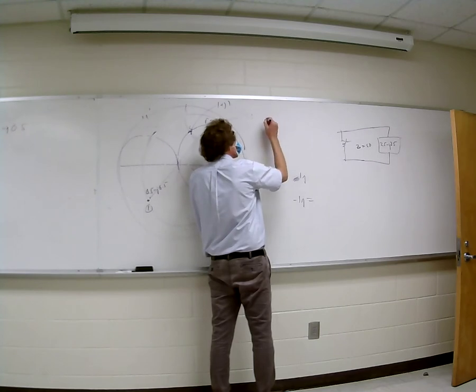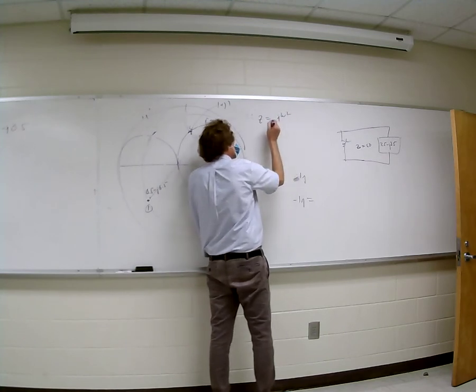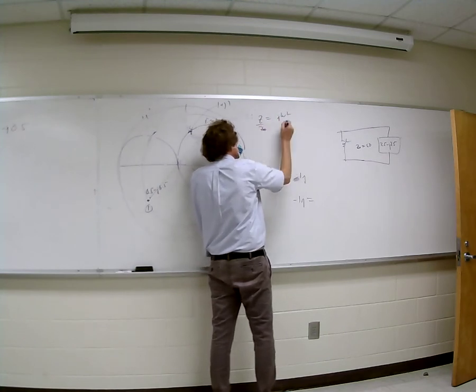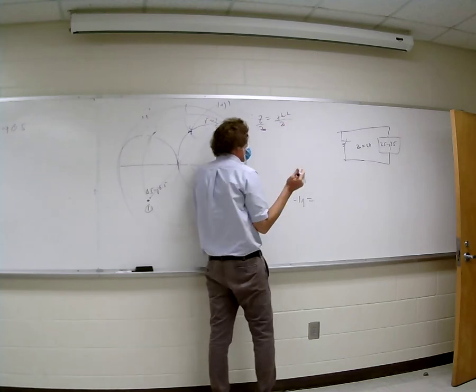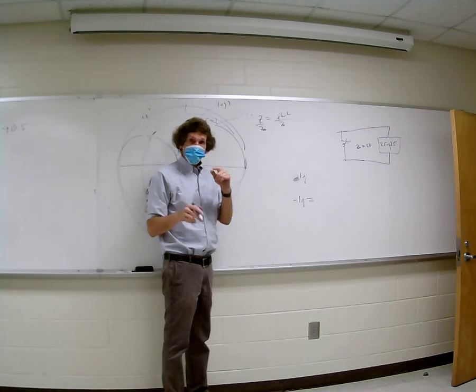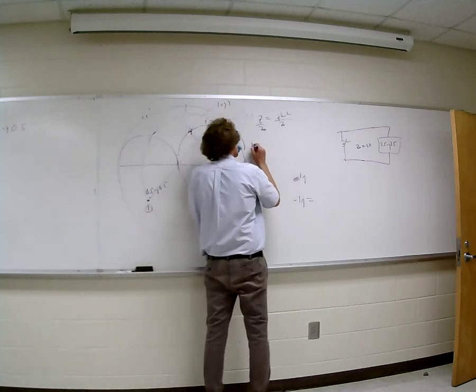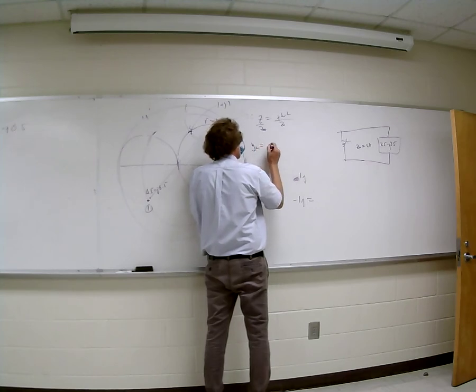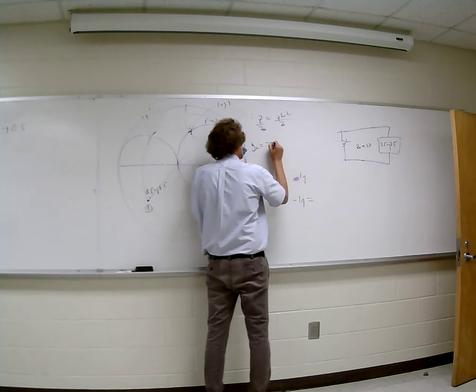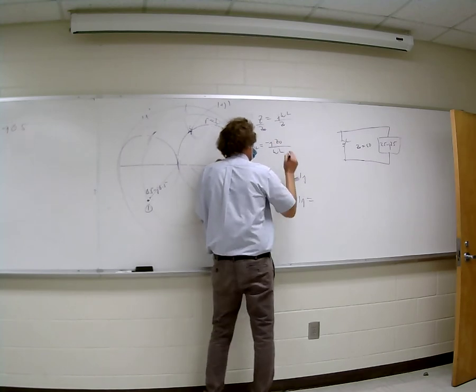I start with the impedance of an inductor, which is J omega L. Then I divide it by Z naught. Now that's the normalized impedance of the inductor, right? The admittance of the inductor is 1 over that. And so Y of the inductor would be equal to minus J, Z naught over omega L. Do y'all agree with that?